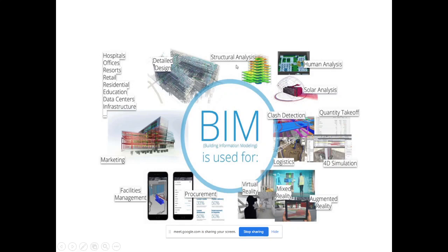The structural analysis is done in Robot Structure. Clash detection is done in which one? Navisworks. Okay. For what purpose is clash detection used in BIM? Any clashes in your building, between beam, column, slab. You simply created the G plus 20 or 40 floors. You do not go directly to find the clashes between beams or anything. But you simply see in your software and easily find any clash detection in your software. For that purpose you use clash detection software.